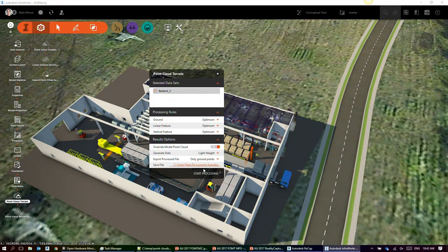So then if you want to use another tool that's more traditionally used to create a surface, like Civil 3D, you can do it on something that's already had the separation done really well. That's where Civil struggles a bit, but Infraworks does it quite well. So as a data cleanup tool, between Recap and Infraworks, you can do quite a lot, especially for the site-type projects.